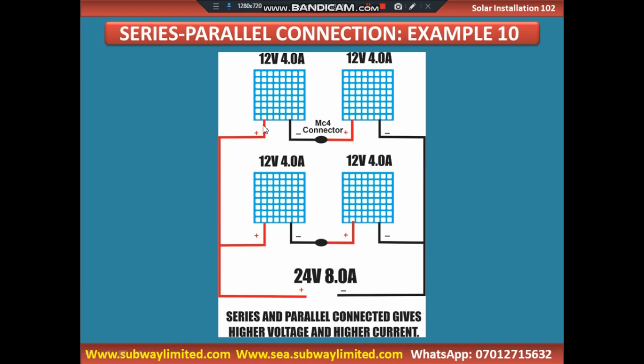We come and connect the positive of this one. We link it to the output cable, and we link this one to the output cable here. This is pictorial illustration. If it were to be real life installation, we would have used MC4 connector. When we move to the practical session, we will show you how to go about this, and you get to understand.